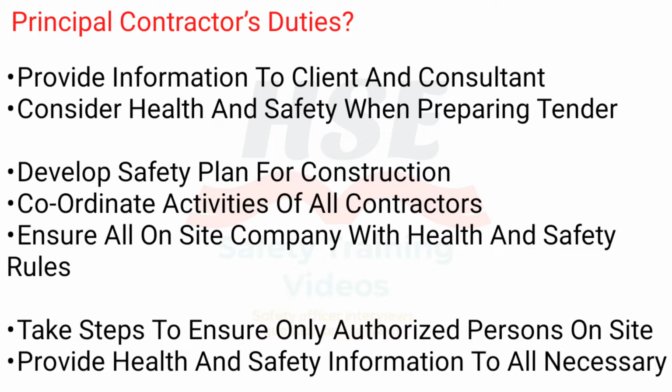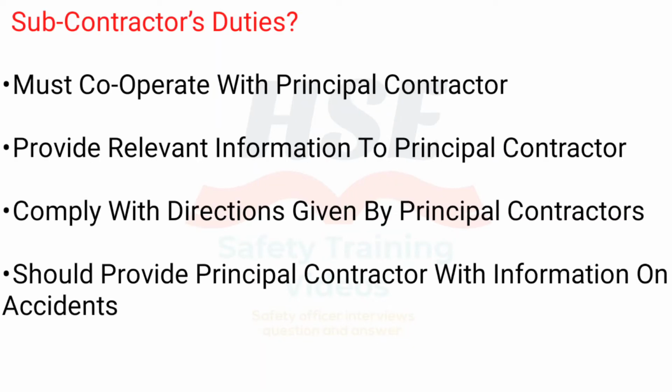Principal contractor's duties. Provide information to the client and consultant. Consider health and safety when preparing the tender. Develop a safety plan for construction. Coordinate the activities of all contractors. Ensure all on site comply with health and safety rules. Take steps to ensure only authorized persons are on site. Provide health and safety information to all who need it.